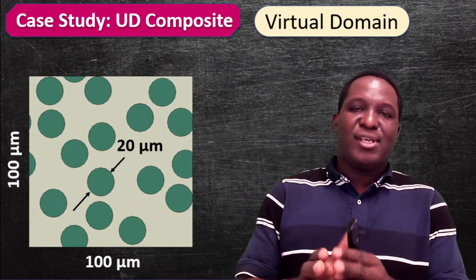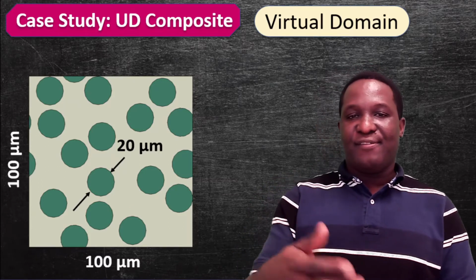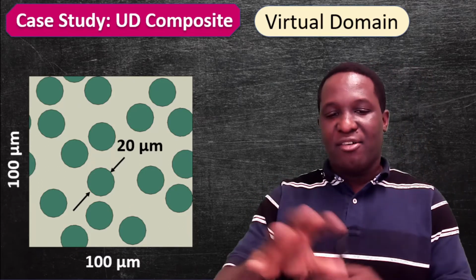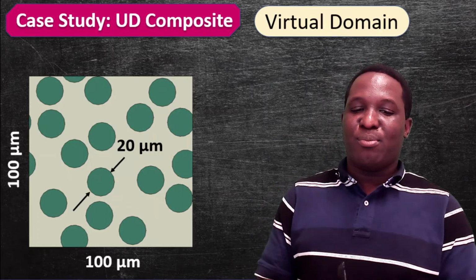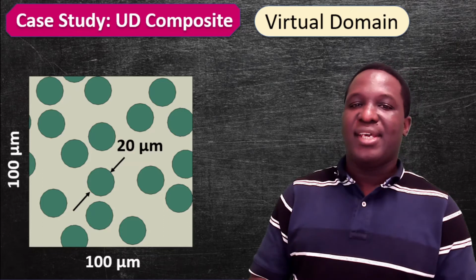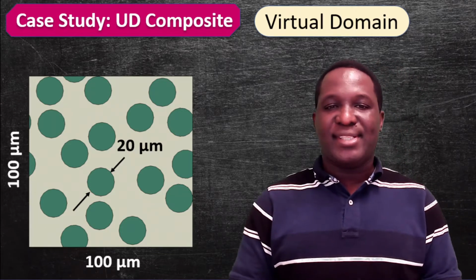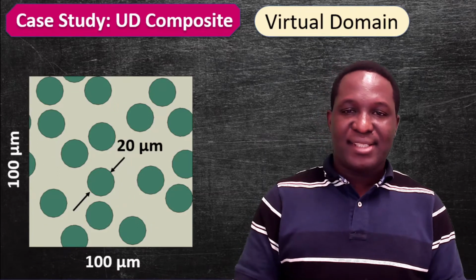So to illustrate this, the first thing we're going to obviously have to do is to think about our case study. So I'm looking at again a UD composite, and this UD composite will have a virtual domain that looks like here, random distribution of fibers within the domain. The fibers would have a diameter of 20 microns. The dimensions of this system is about 100, 120. We'll look at that when we start the simulation.